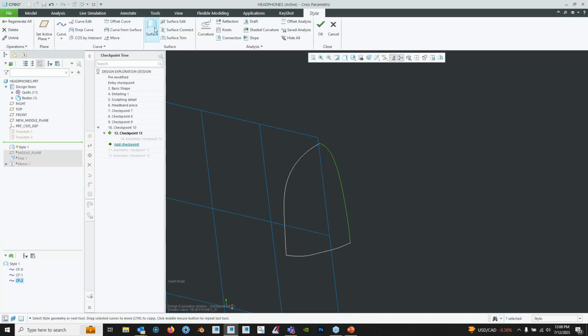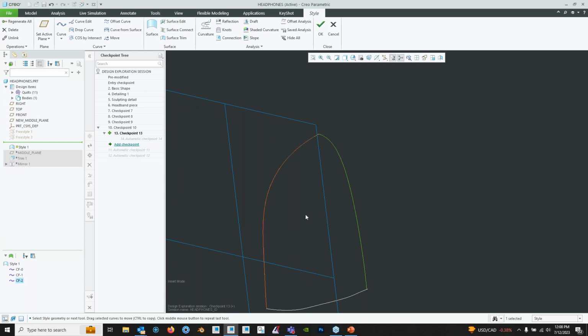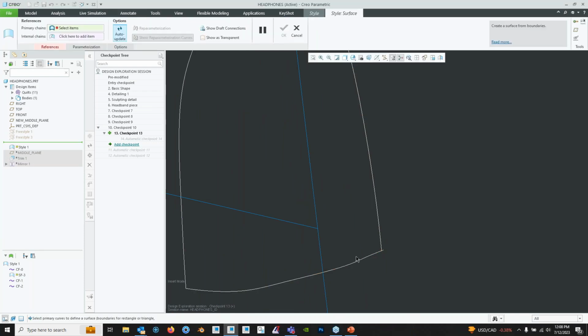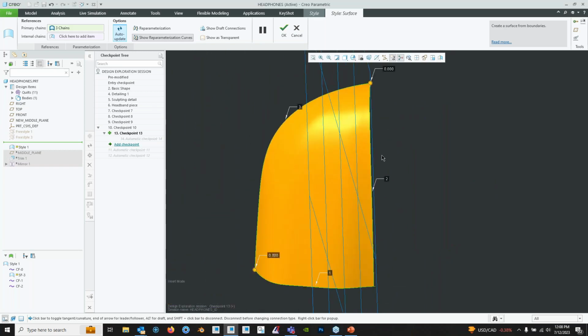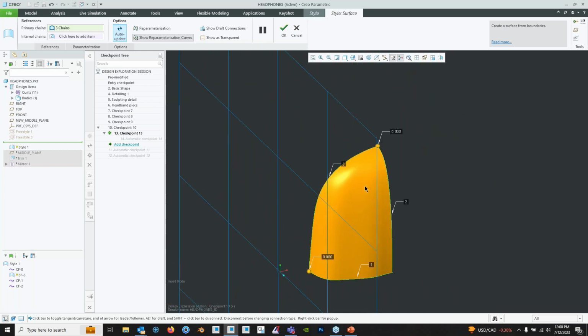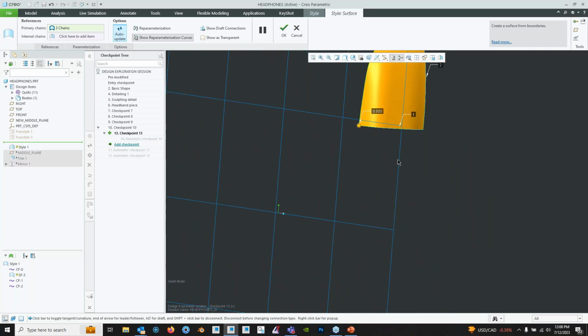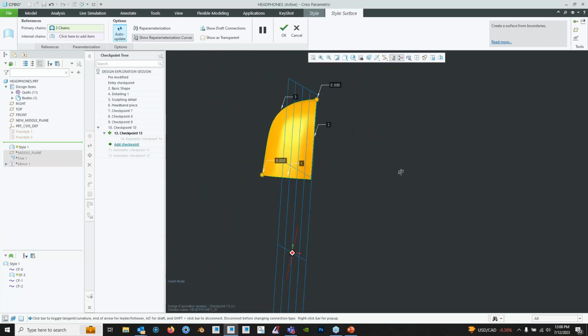So now that I have this, there's a surface outside of this tool. It's called boundary blend, but it does basically the same thing. So if I choose this, might not do it because that's off just by a bit. But what I would do is I would select these three curves, and it'll create a surface. So some of you might call this a patch, and here it's called a quilt. And as I would go along, I would continue to make several quilts and several patches to start building like that outer piece of the headphone.